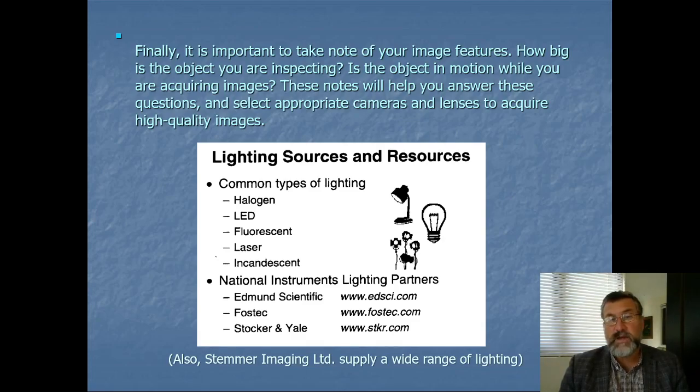There is one advantage a halogen might have over an LED, which is that a halogen light, or a conventional bulb, produces a continuous spectrum. Because the filament, a tungsten filament, is actually a black body emitting radiation at a temperature of 5,000 Kelvin. So it's got a continuous spectrum of wavelengths. So if you want a particular wavelength, you can always get it from a halogen light by means of filtering or just selecting certain wavelengths. Whereas LEDs have specific wavelengths, they don't have such continuous bands, they have more discrete bands. So that can sometimes cause a problem. So sometimes you do need a continuous spectrum.